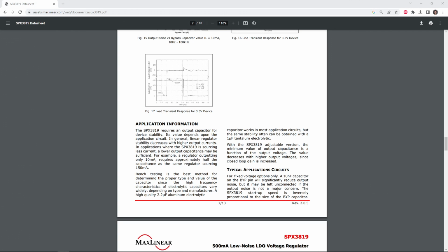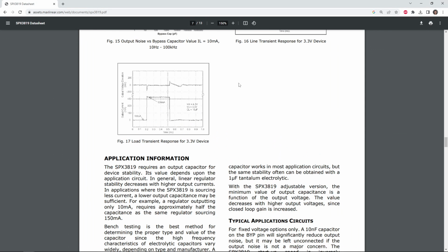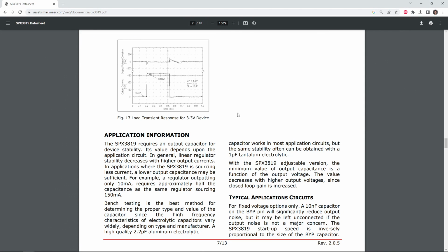What's very important also with LDO regulators, and it's a fairly easy choice to make, is the choice of input and output capacitors. Typically, any sensible datasheet will give you recommended values and minimums for these capacitances. Modern LDO regulators will allow you to use very small, multi-layer ceramic capacitors.